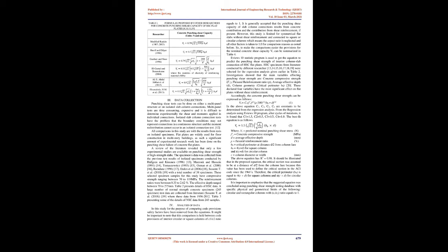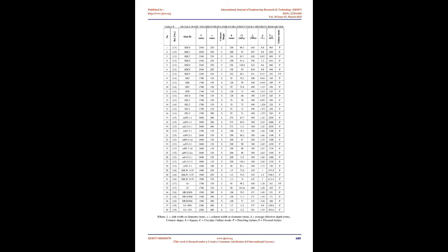Research significance. Punching shear is a very important issue, especially in flat plate slabs. Errors in predicting the punching shear have been shown to lead to catastrophic failure. Different codes have discussed the punching shear provisions with great importance. In recent years, the use of high-strength concrete, HSC, is becoming more and more popular. Increased use of HSC is faster than the development of appropriate design code and recommendations. Several recent studies showed that HSC has different characteristics than NSC.